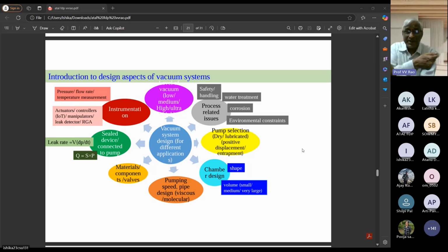And they are non-interacting because the mean free path is very long, kilometers. They will only hit multiple reflections in the body of that pipe, but they won't hit each other because you're already below 10 power minus 3 torr. Thermal vacuum is up to 10 power minus 3 torr. That is good enough for flask making.